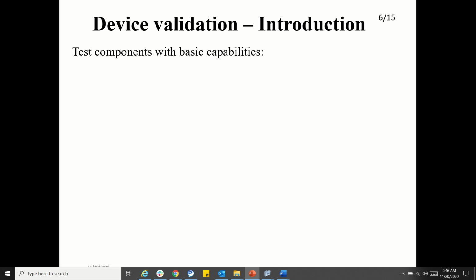They have minimum requirements that I have been mentioning several times. The first such thing is ACLR, adjacent channel leakage ratio. The second one is channel power. Channel power should come first. Basically, first we check the channel power, because within our band we need to know what power is being transmitted.